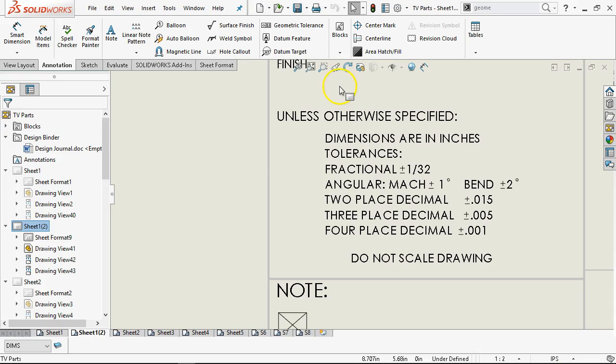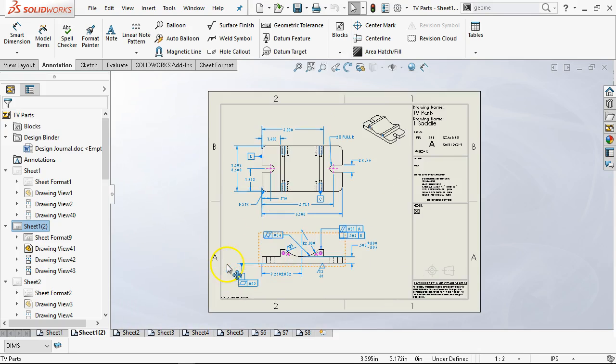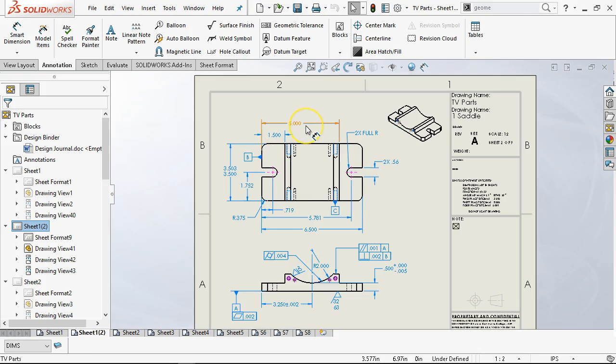All right, so one of the things I say quite often with the tolerances is if you default to 4 decimal places, this is a legal document. This is a contract. I'm accepting the work on this document, and if there are 4 places here, you can come back and hold me to it. So I make the point, and it's kind of a mean point, but people that send me 4 decimal place tolerance drawings, they get a quote that is, I'm going to hold 4 decimal places to your tolerance on all of these dimensions. And they go, $100 a piece. Why? Because you put 4 decimal places everywhere and you can legally hold me to it.